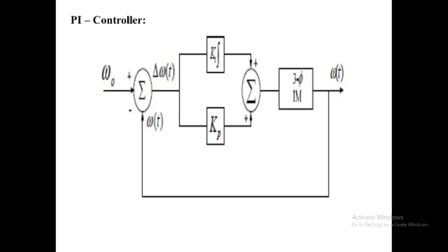Despite these advantages, the PI controller fails where the controller object is highly nonlinear and uncertain. This PI controller will eliminate the forced oscillations and steady state error resulting in the operation of on-off controller and P controller respectively. However, introducing the integral mode has a negative effect on speed of the response and overall stability of the system.